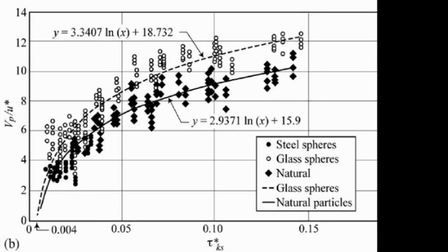And you find here that at those star, remember I said 0.03, 0.047, this should normally be the Shields incipient motion, and you still have particles moving at 7 times the shear velocity for those conditions. And you can get incipient as low as 0.004 for the Shields parameter.